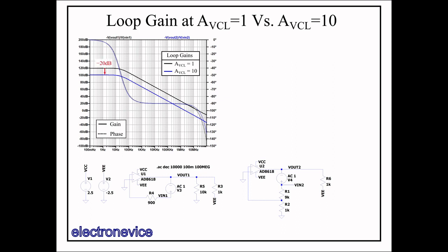We see that the gain is lower than the open loop gain transfer function by about 20 dB throughout the entire range of frequencies, which makes sense as the beta value for the gain of 10 amplifier is 1/10, which is equal to -20 dB. Note that the phase looks almost identical, which also makes sense since beta shouldn't change the locations of poles and zeros in the error amplifier prior to gain crossover.